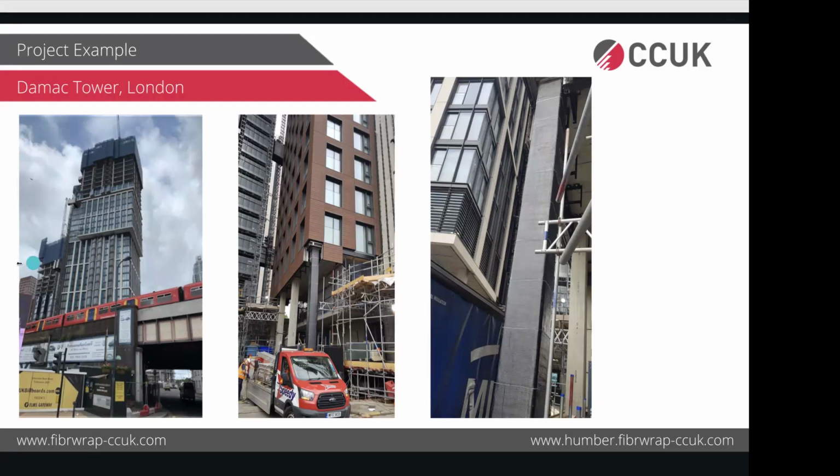What happened was that there was supposed to be a link bridge between these 2 tower blocks. That link bridge was going to be a precast concrete bridge, which had no connection with these 2 buildings. But in the end, the client changed his mind and wanted a steel bridge instead. Now that steel bridge needed a connection with this column. A plate needed to be connected here on which the bridge can be connected. This column is not designed for that load and needed strengthening.